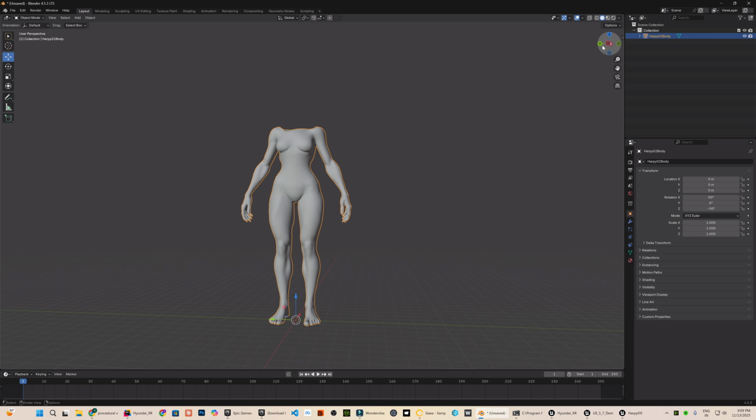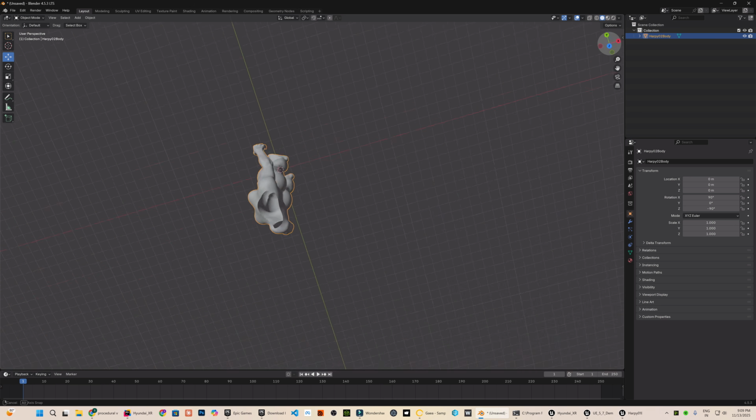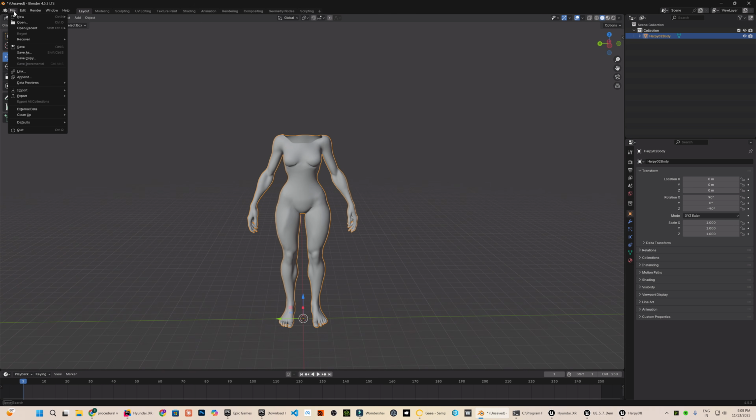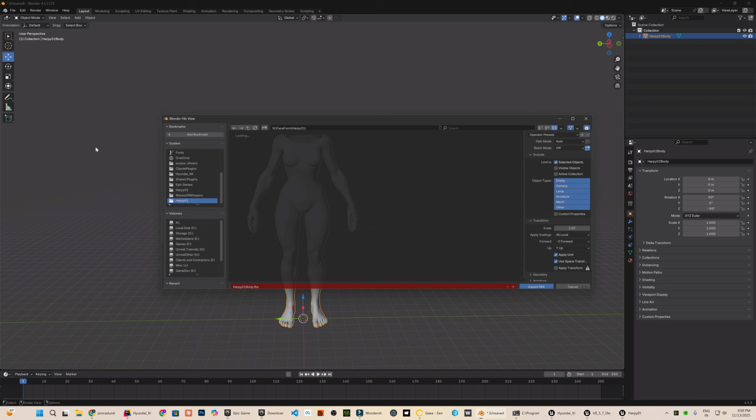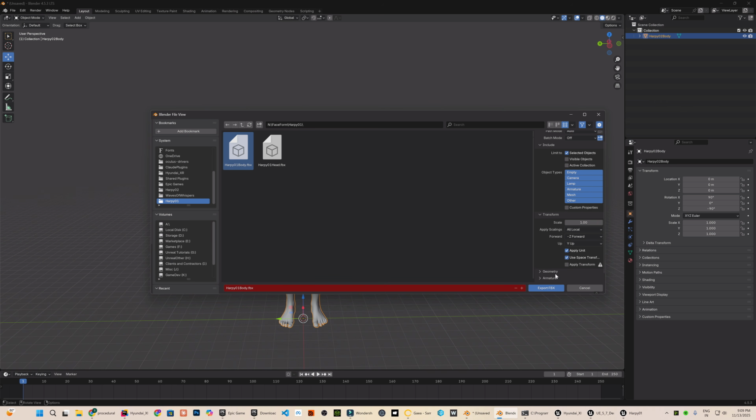I'm switching to Blender now because I noticed a strange issue in Unreal Engine 5.7 where OBJ files do not import with the correct transformations, even if you add the offset transformations in the import settings. Until that bug is resolved, I need to convert both the head and the body back into FBX before bringing them into Unreal.